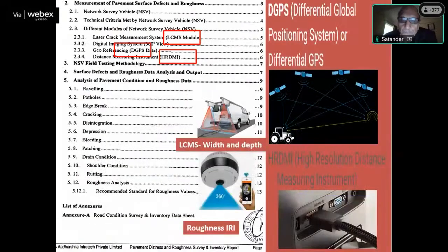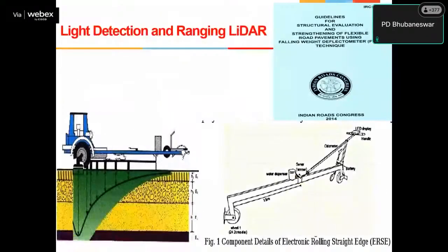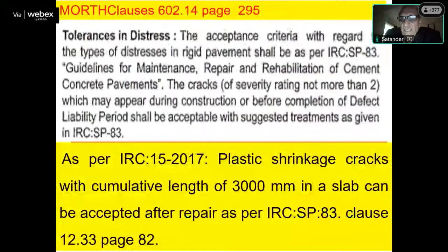जी, what are the permissible limits of bulk density of fly ash for backfilling in RE wall portion? Actually, that slide went a little bit faster. We could not see the permissible limit of fly ash in RE wall. In RE wall, fly ash as per IRC 102 is permitted. There are actually 3 soil types. Please remember, I am talking about permissible bulk density limits.